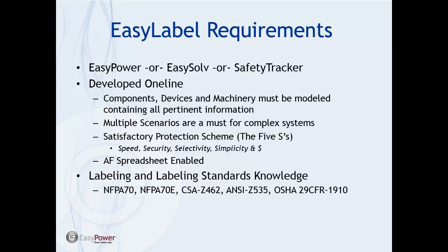The second thing that we'd want in that developed one line is to make sure that we have multiple scenarios, and anytime we have a complex system, it's really important to analyze and monitor every scenario that we could possibly present, or at least the worst case scenarios that could be presented in which we're going to get different arc flash results.